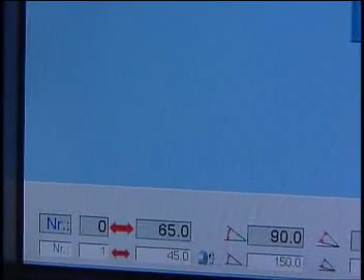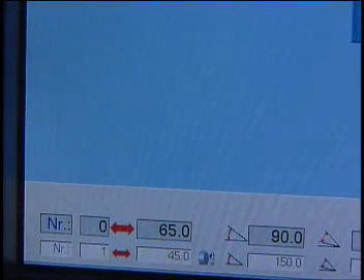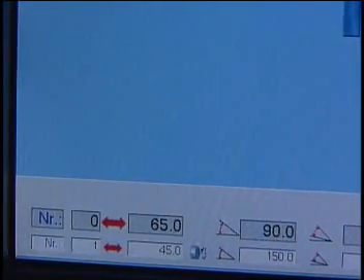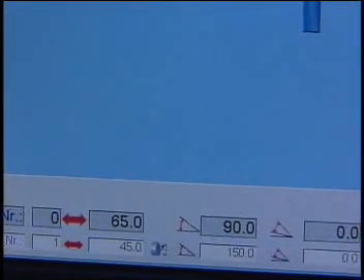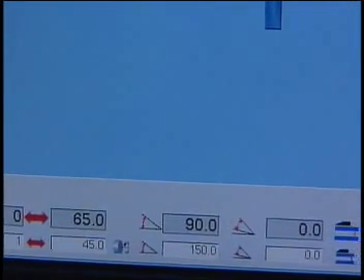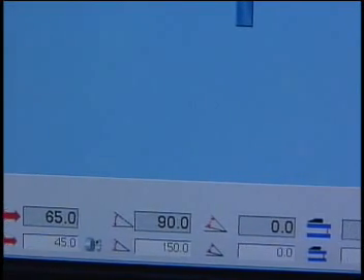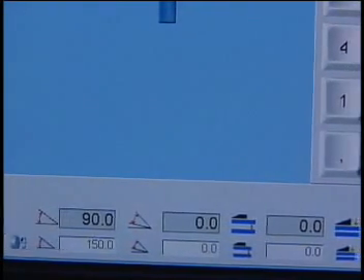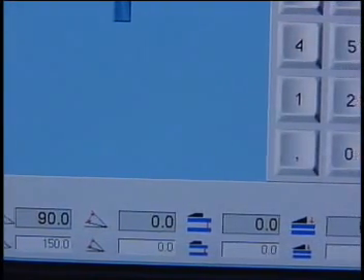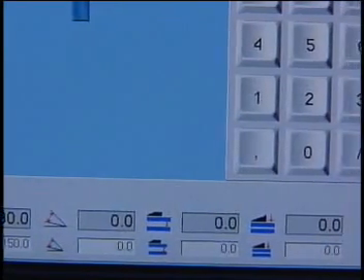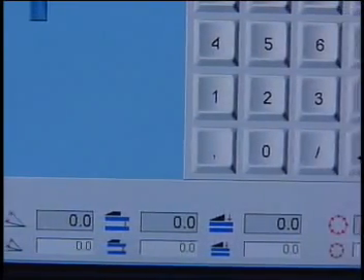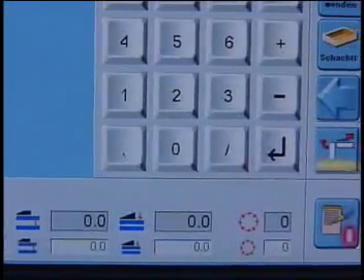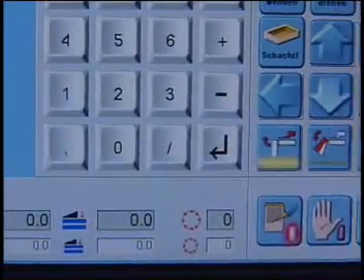At the bottom of the screen, you will find the actual and the following program line of the present profile. Each line has a subsequent number, value for the back gauge, symbols for material rotations, and a column for the bending angle. The bending angle correction compensates the material spring back when doing radius work. Upper beam lift up is important when parts must be turned around. And so is the column for open hems, and the final column for the number of loops to form radius.